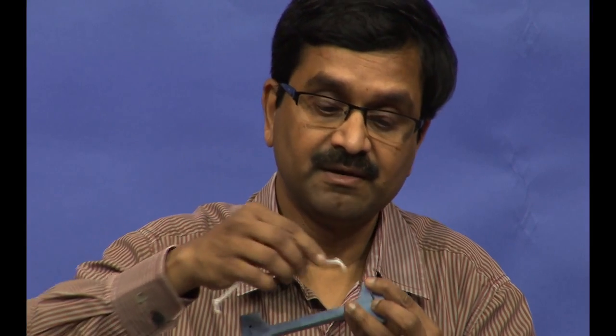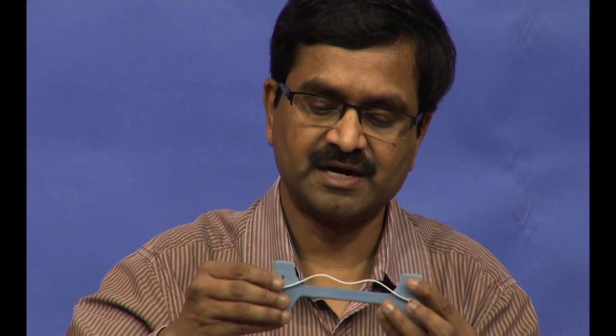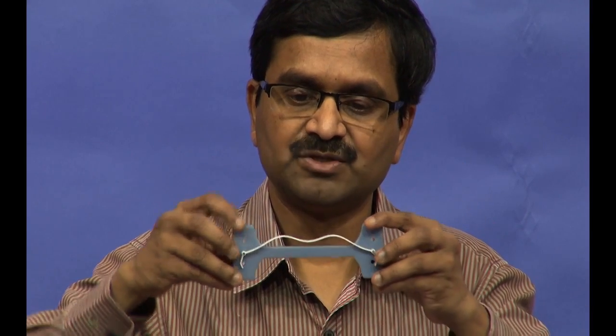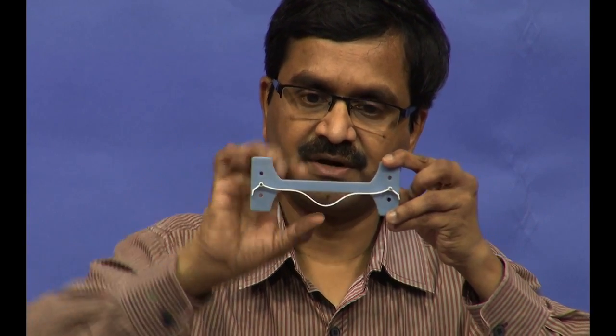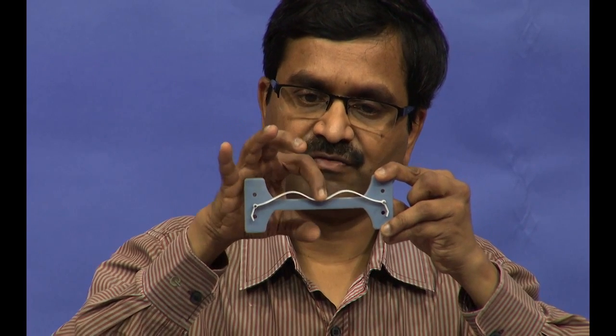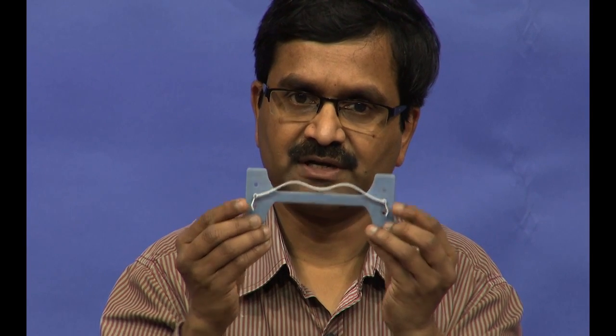There are different curves, different arches we talked about. If you take the buckling mode shape of a straight beam, here is actually the combination of the first and third modes, it looks more like a bow. So, this particular one, this is one stable state, apply a force, it goes to the other stable state. Okay. Apply a force back again, it comes back, right. Now, if it is here, I can also apply the torque here and it switches.